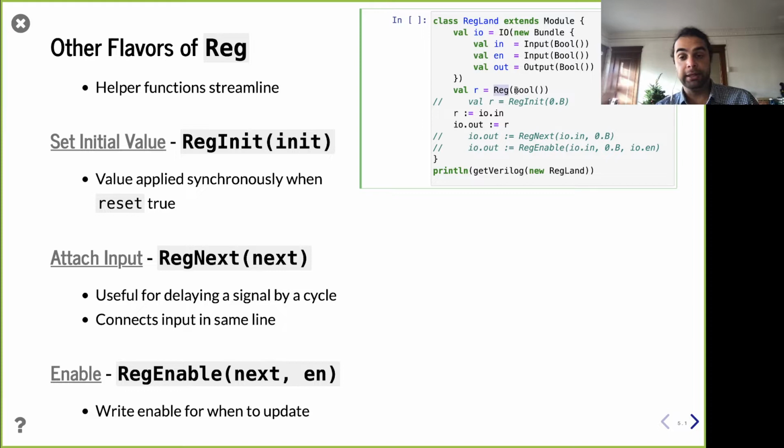That's how the tools know how big to make it. So for example, you can say, yes, it's a Bool. Okay, so it's a 1-bit thing. So at this point, it's declared a 1-bit register. And this is a Chisel logic floating. We have a Scala reference to it in case you want to point to it later on, right? But think about it as a piece of hardware. Okay, we have a register.